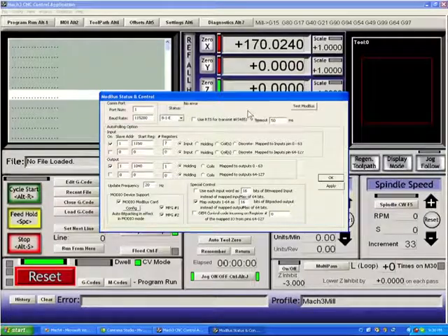First of all, let's take a look at what's in here. Here we set the serial port number that we're going to talk to the ModBus device with. Here we have the baud rate, which is going to be the communication rate to the device. This baud rate is specific to the configuration of the ModBus control or the PLC that you have. One of the first things to do with any ModBus or PLC device is to set these settings and then test your ModBus to see if you have communications.